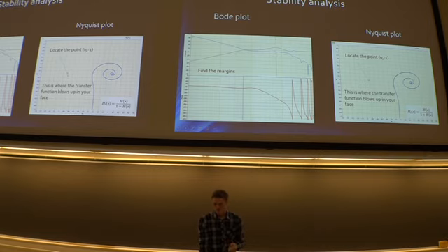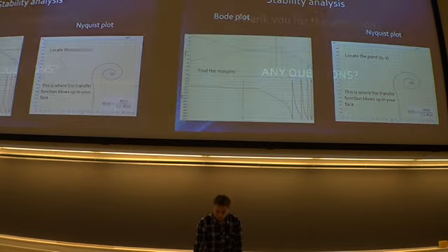Also, you can look at, this is the same thing actually, this point, which is the imaginary frequency in the transfer function. When the open loop transfer function becomes -1, it blows up to infinity and it starts oscillating and amplifying, and then boom, it goes all the way. Thank you.